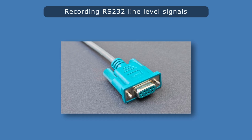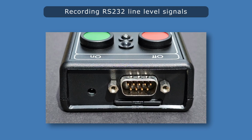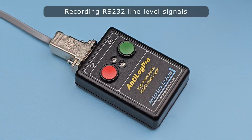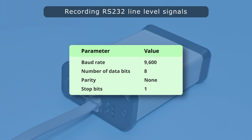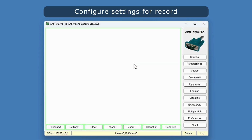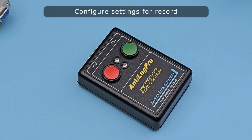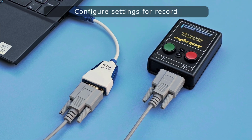To log RS232 line-level NMEA sentences, you'll need a data recorder that supports RS232 line-level input signals. For this video, I will configure one of our AntiLogPro RS232 data loggers to log a GPS NMEA data source at 9600 baud, 8 bits, no parity and 1 stop bit. First, set up a terminal application on your PC ready to interact with the data logger's menu system. Disconnect other devices connected to the data logger and instead attach a null modem cable. Connect this to an RS232 port on your PC.